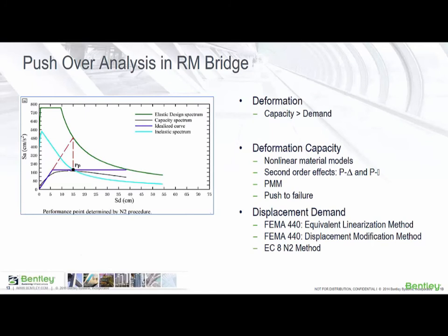Pushover analysis in RM Bridge. Pushover analysis implementation in RM Bridge includes rigorous deformation capacity calculation. It offers three methods of calculating the displacement demand, namely FEMA 440 displacement modification method, FEMA 440 equivalent linearization method, and Eurocode 8 N2 method.